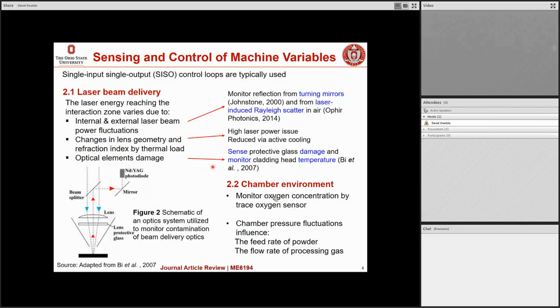This is usually caused by the laser hitting the substrate, which can give some vibration or gas emission that will affect the lens. So usually they will use a lens protective gas to protect the lens.